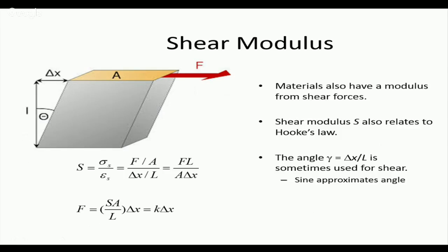Apart from the elastic modulus or Young's modulus, we have the shear modulus. Shear modulus is shearing stress divided by the shearing strain. Shear force is acting on the top, as you can see, and it is acting on an area, in plane. Here the shear is acting in plane. The force acting on this area will give you some shear stress, and with the shear strain you can calculate the shear modulus.